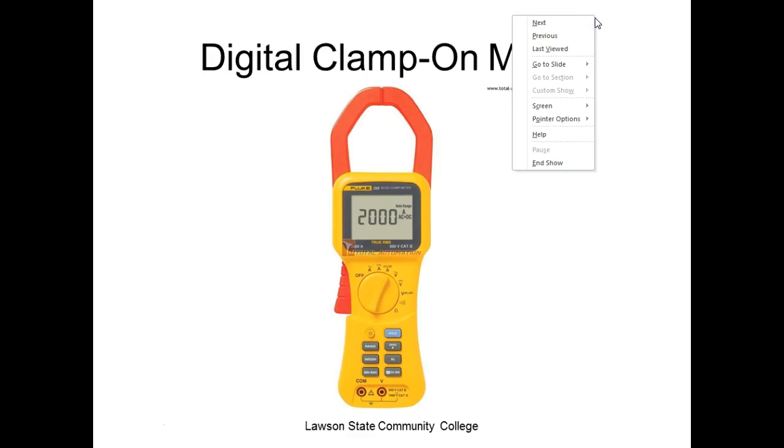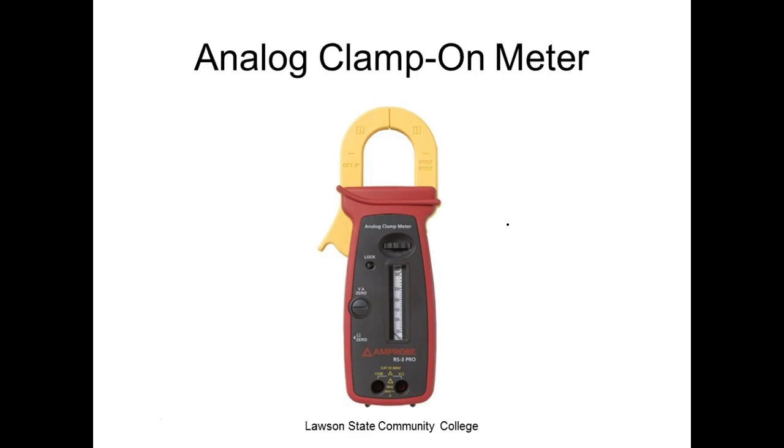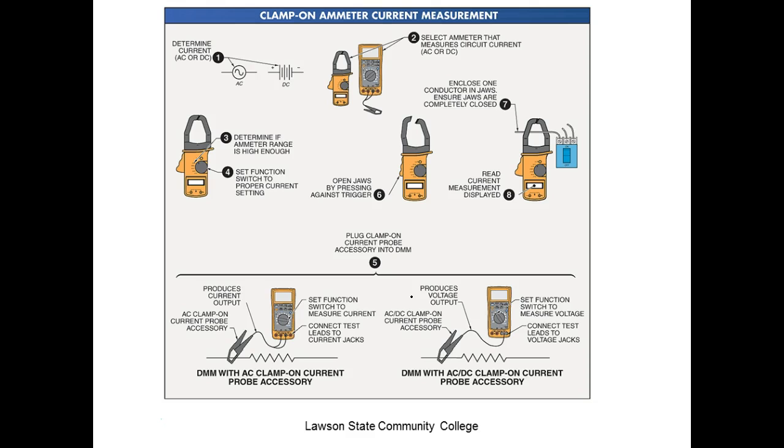So this is the clamp-on amp meter. I can't see the category on this. This is a Cat 3, Cat 4 meter. And of course you can also get those as an analog meter. These are clamp-ons. They're really nice, but very few of them go down to very low current scales. They work good in high current applications. They're a lot safer because you don't have to do what? You don't have to break a circuit.